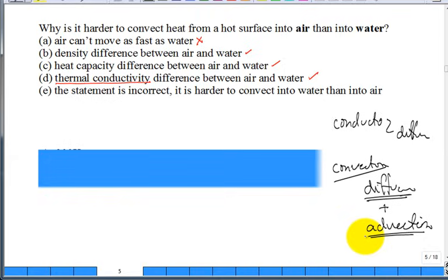What do we know about no-slip boundary conditions from fluid mechanics? How fast is the fluid flowing that's immediately adjacent to the solid? It's not flowing. So how does it get through that stagnant layer of fluid? It can be a very, very small stagnant layer, especially if the fluid flow is turbulent, ripping it up and chewing it up. But it's really that zone right there that often controls it. It has to be through diffusion or conduction to get heat in there. It's a combination. Convection is conduction with advection.